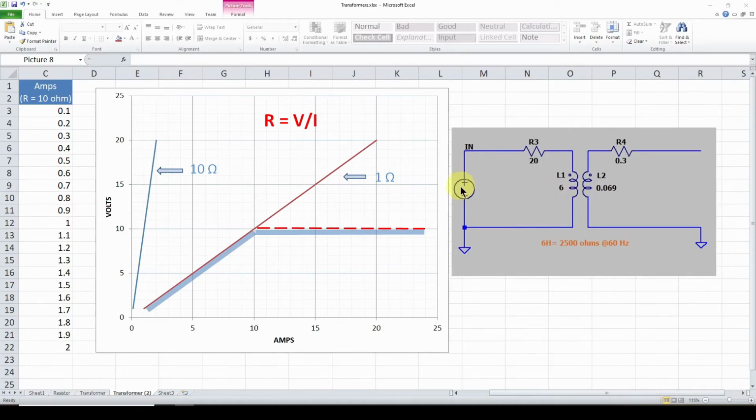So, for example, if I had 200 volts across here, we might get up to 10 amps because 200 over 20 is 10. So instead of the normal 47 milliamps, we might get 10 amps or 20 amps, depending on how much voltage. So our challenge is to figure out what kind of characteristic, voltage versus current, this transformer has so that we can model it.